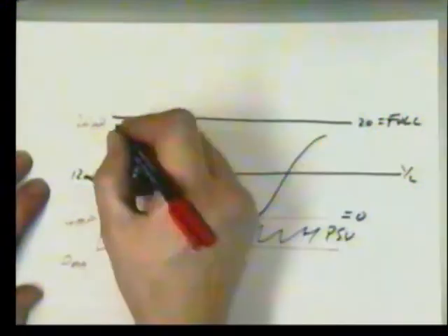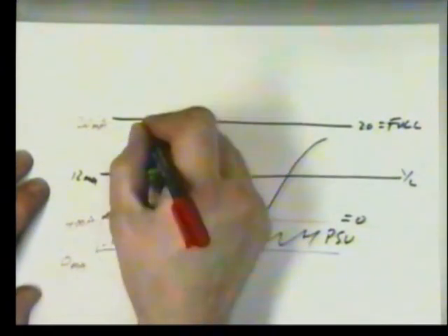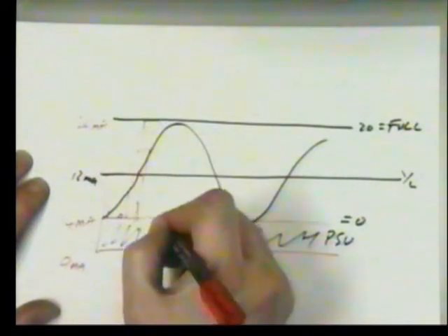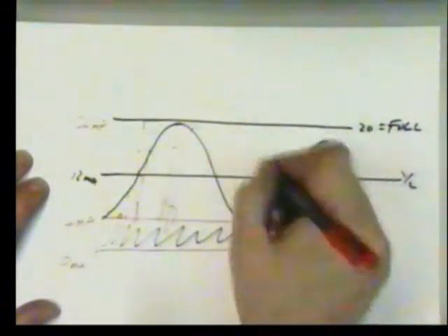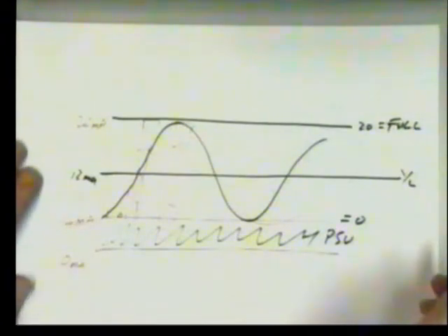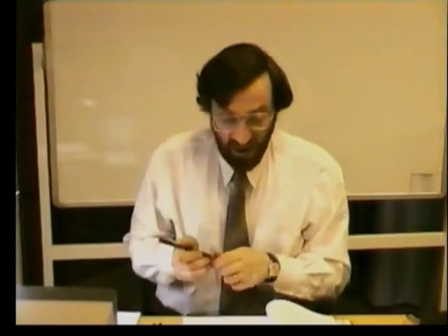That is the traditional analog two-wire system. But of course, with modern techniques, we'll have digital signals. If we treat that as a logic level 0 and that as a logic level 1, we now have the ability to transmit binary data in the current loop area, transmitting data back to the remote system digitally if we so wish. Let's just have a brief review of transmitters.